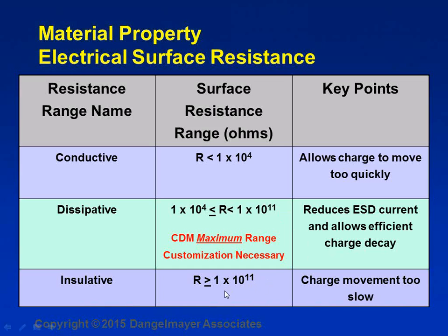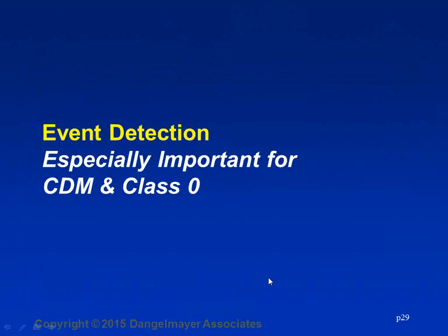And as you know, insulators are static generating and are very slow to remove charge and therefore leave the device charged, ready for metal-to-metal contact to cause damage.